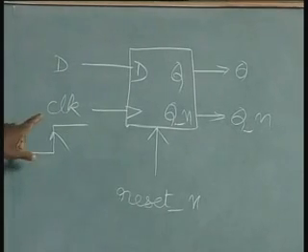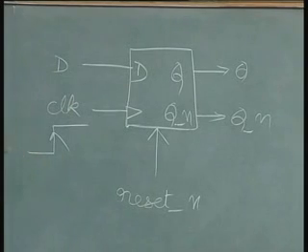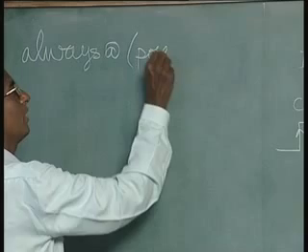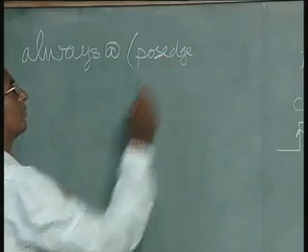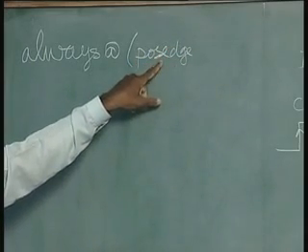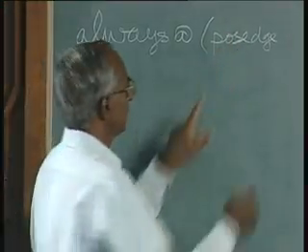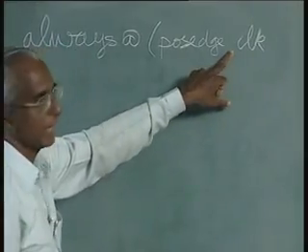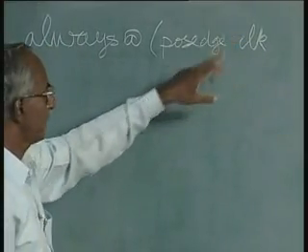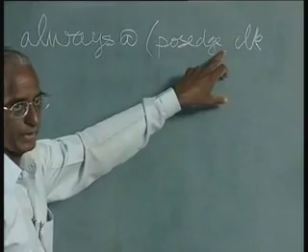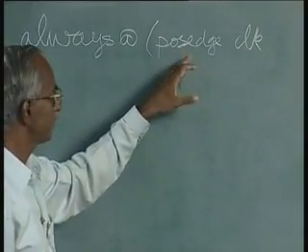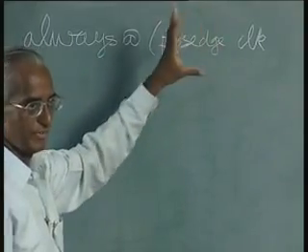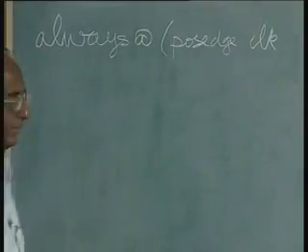For example, you want this at positive edge. So what we do is use a reserved term in Verilog called posedge. Note this. If you make a spelling mistake, naturally the tool will complain. Now we give a blank, one or more blanks. At least one is mandatory, otherwise the tool cannot distinguish between the two words. And don't put an underscore or any other symbol, just a plain blank.